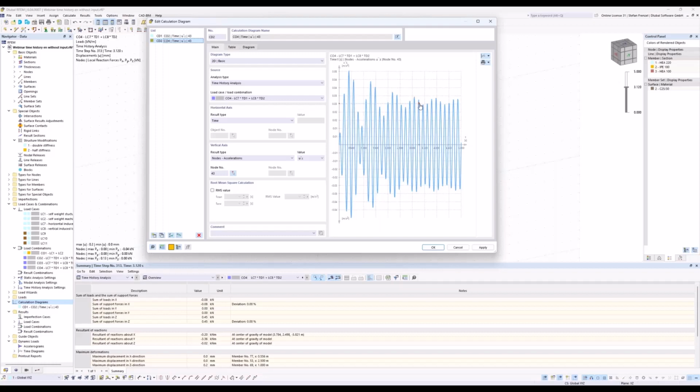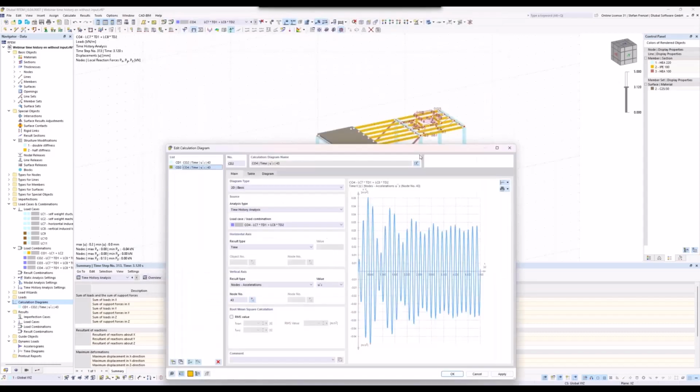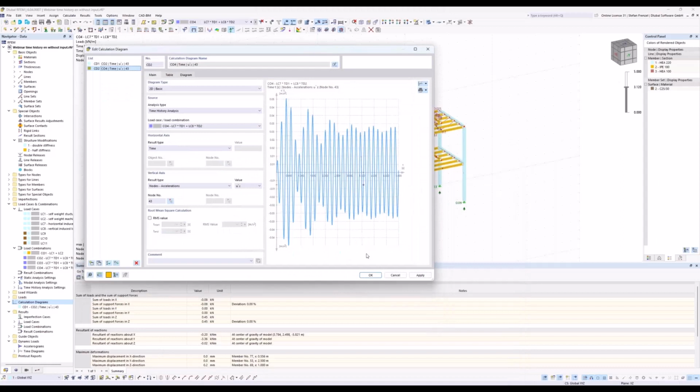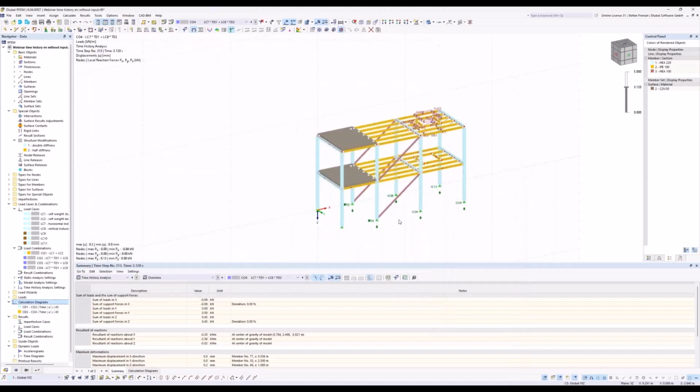So in this case, just by changing the bracings, you will be able to work with this machine on this structure, because the induced vibration of this machine is then not a problem anymore for the structure. But it's always good to have a look at such things, because here, of course, nobody could notice that we get an induced or resonance case for such a machine when I put it on the structure.